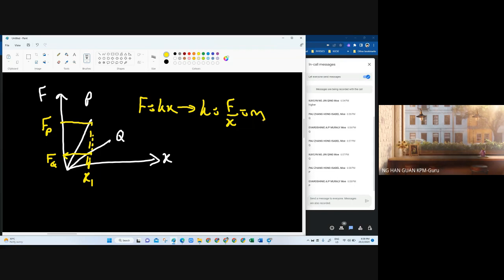When you have a bigger diameter of coil, the spring coil has a bigger diameter, so you make a softer spring. When you have a smaller diameter of wire, it means you're using thinner wire. Thinner wire will make the spring softer also. All right, so bigger diameter of coil, softer. Smaller diameter of wire, softer. So please be careful about the factors that affect the stiffness of the spring.